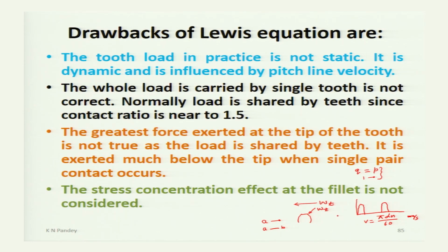Now, at point B, when the previous gear teeth disengage, the normal load Wn has travelled some distance down to the tip of the gear. Therefore, at the start of engagement at point A, there will be sharing of the normal load Wn by another pair of teeth at B.